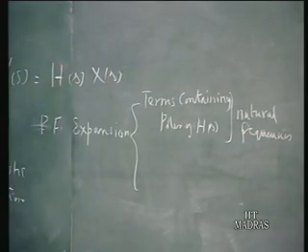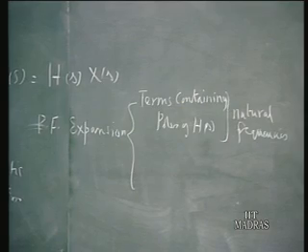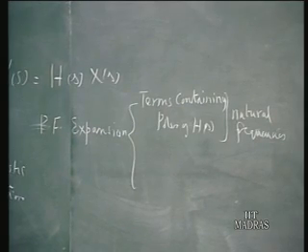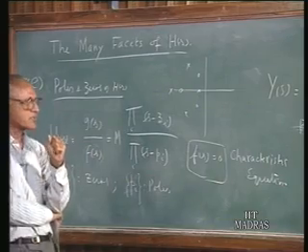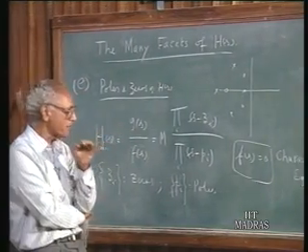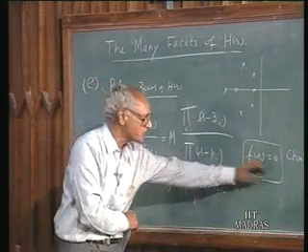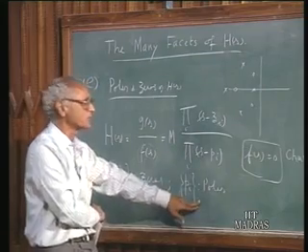They are the p i's here. They are the roots of the characteristic equation. So the natural frequencies of the system are the roots of the characteristic equation. When I talk about natural frequencies, I'm talking about frequencies in the complex domain. They are the poles p i.